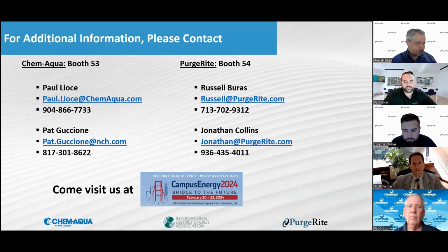Yeah, and from a chemical provider standpoint, air handler units, coils, things like that, we would love to see that get cleaned and passivated. And that goes back to that earlier topic of okaying it with the equipment manufacturers, right? Saying that it's okay to do this flushing. Right. And a lot of times we submit the chemistries to them, which then they see don't really pose any harm to the mechanical issue, so it won't void their warranties. But it's just going through that process and giving yourself enough time.